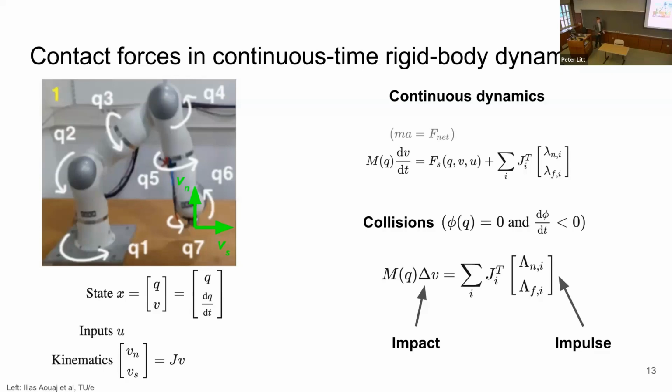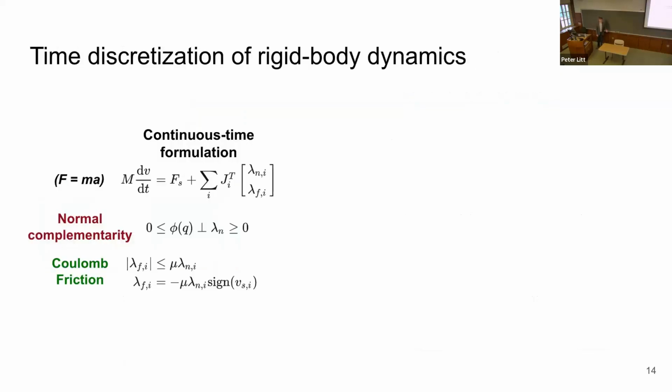So this equation here on the top right looks something like a differential equation. But differential equations are not enough to model these systems, because if you assume that bodies are perfectly rigid and they come together with some non-zero velocity, then there is no solution or result that could happen to prevent interpenetration except a sudden instantaneous change in velocity. That change we would call an impact, and it's the result of an instantaneous accrual of a non-zero amount of contact impulses.